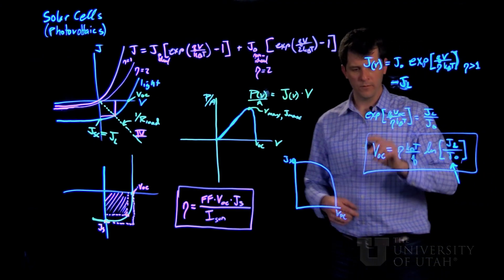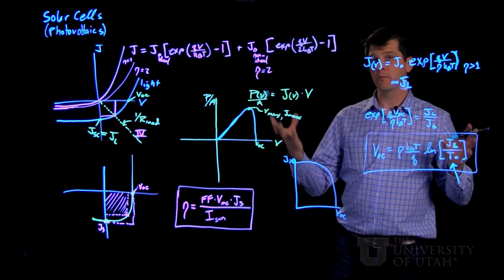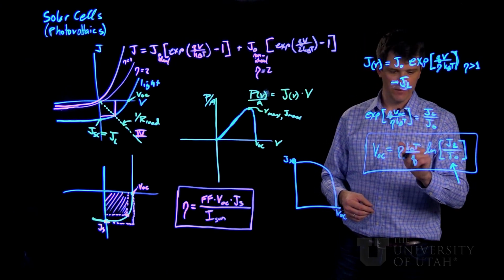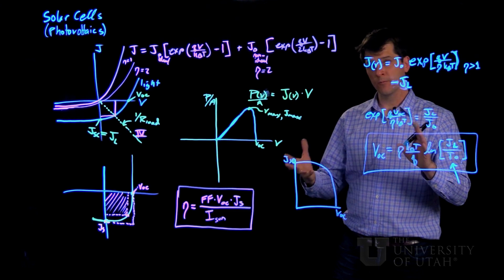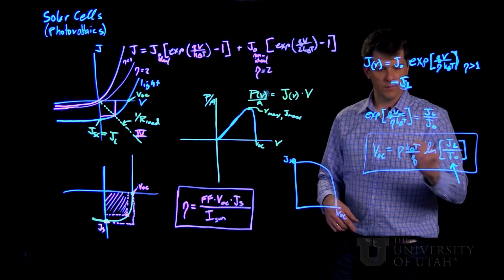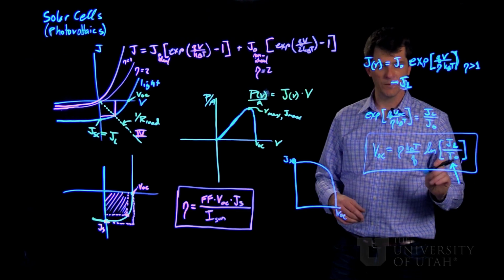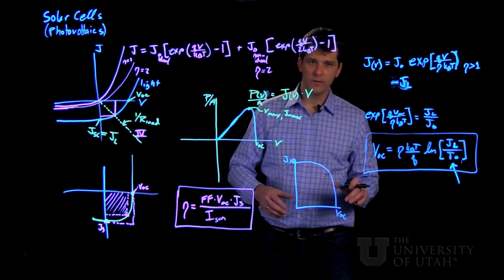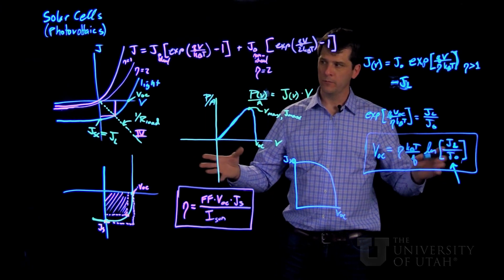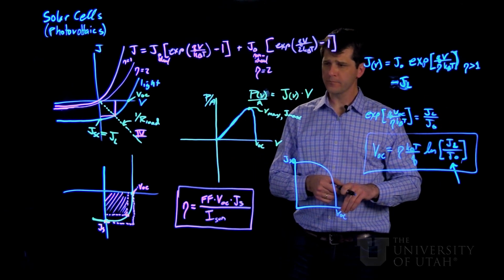So the name of the game in photovoltaics is to reduce this dark current by eliminating all sources of recombination generation and making your diodes as good as possible. Now, it may appear here that making eta bigger than 1 is a good idea, but this effect here greatly outweighs it. This is a linear scaling, whereas this is usually many orders of magnitude change for a tiny bit of recombination. So, in conclusion, to make good solar cells, we want to reduce recombination everywhere in the material and its boundaries, the surface recombination as well as all sources of bulk recombination.